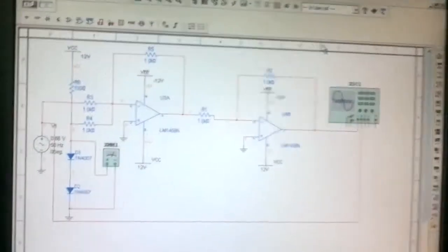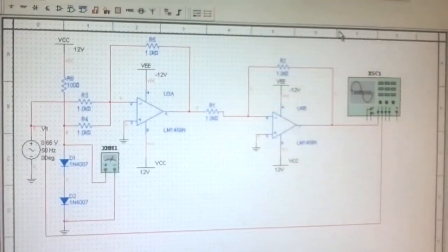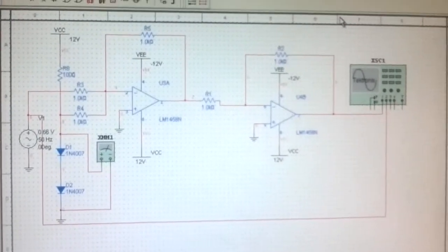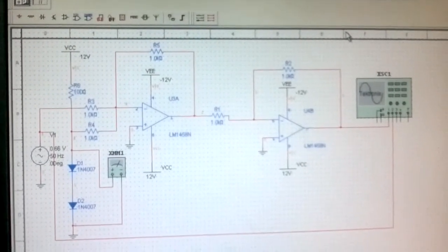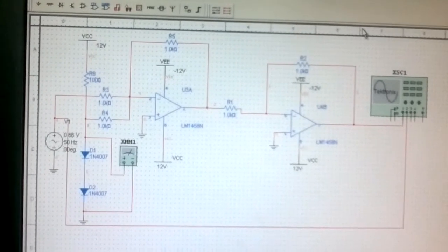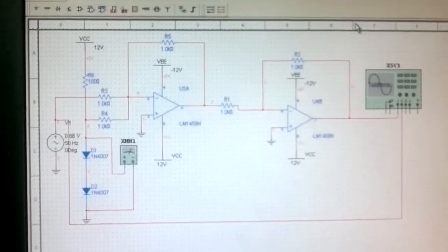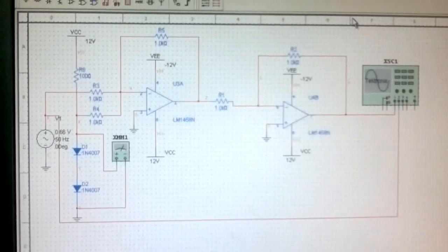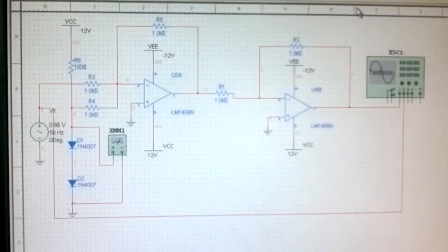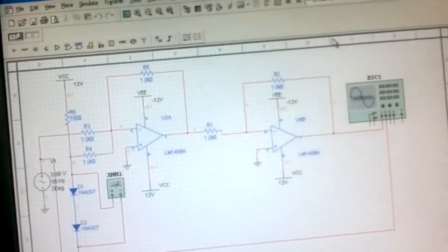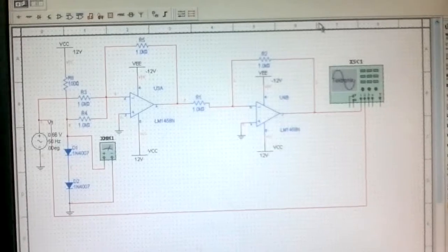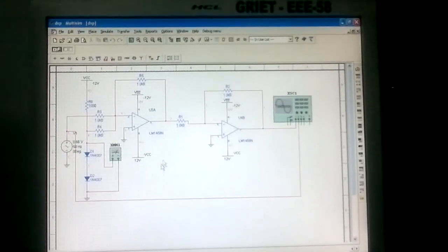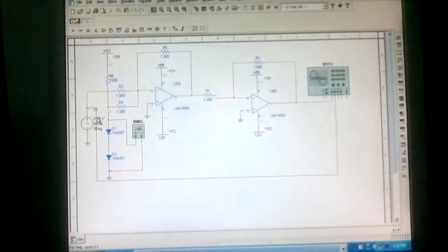This is a circuit for voltage and current signals data acquisition. The circuit is designed so that it can modify the rated 3-phase voltages and currents obtained from the supply of 415 volts 50 Hz in such a way that they can be given to the DSP. The DSP works only with inputs with values less than 3 volts. Also, the signals given as inputs to the DSP must be entirely positive, that is, there should not be any zero crossing in the signal waveform. The circuit here gives a DC sinusoidal output which has a peak-to-peak value of approximately 2.7 volts.